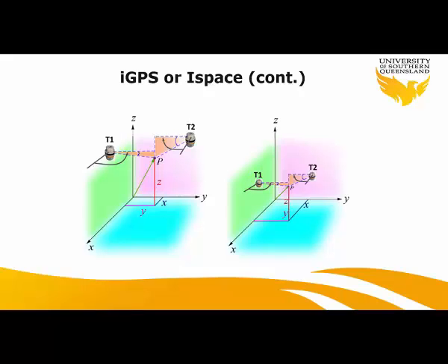To get the unique point using the two transmitters in iGPS, we still need extra information like the coordinates of the station, also the known distance between them, which can be precisely measured by a precise scale bar or invar or carbon bar. I've shown you the scale bar in the macro network when I explained that you're using the scale bar, so you need to have extra information to be able to get the unique position for that point, otherwise you can't.